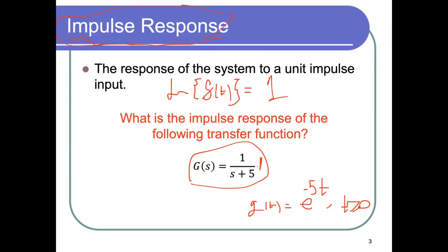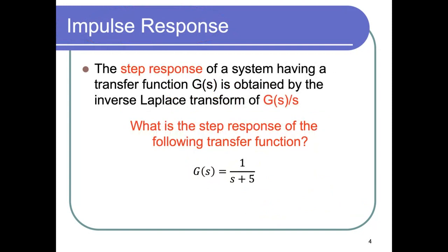The reason I mentioned the responses here before block diagrams is because you can get systems with a lot of blocks. So we can use block diagram reduction to reduce the system into a single block, which represents the transfer function that captures all of the input-output relationship of the system. Then, given that transfer function, analyzing the response of the system using, let's say, an impulse response or a step response, you can know how the system will behave for a given input.